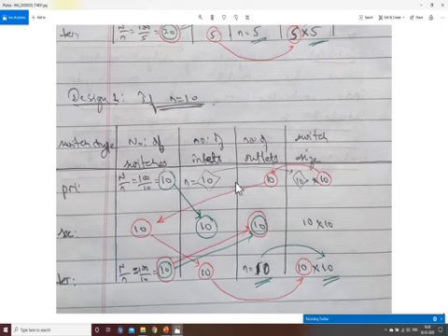Now as discussed, let us assume that the primary switch size is a standard size, that is, since there are 10 inlets, let us assume that there are 10 outlets. So if we consider 10 by 10, then the 10 inlets are specified here, and the switch size is 10 by 10. Now what does this 10 indicate? It indicates that there are 10 outlets, that is, 10 links which are going to the secondary switches. So each of the primary switches has 10 outlets, and these 10 outlets reach each of the secondary switches. So it indicates that there are 10 secondary switches.